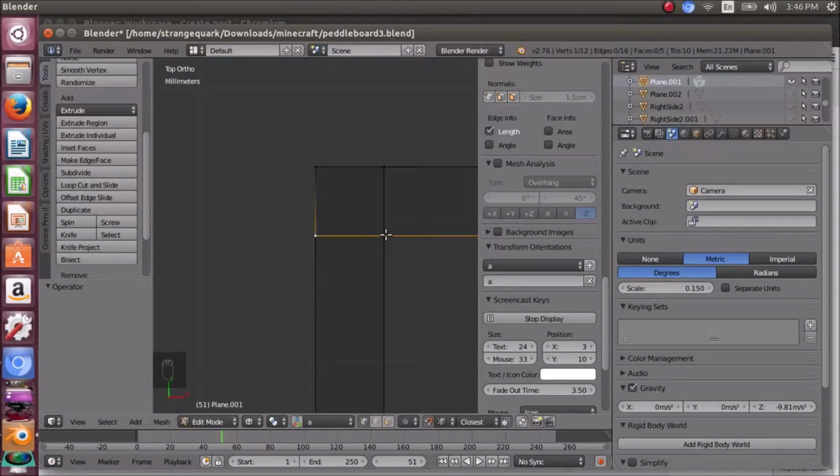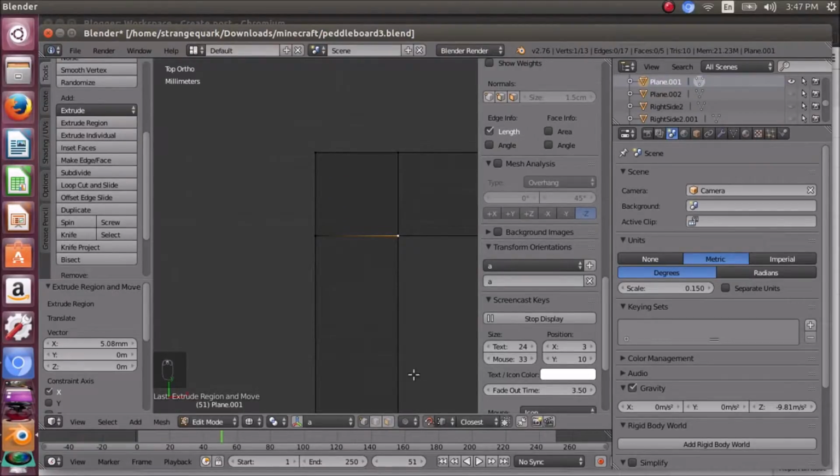So I'll go ahead and select this vertex here and we'll extrude it on the X-axis, and then I'll just run the mouse cursor up to the vertex, and lo and behold, it translates or extrudes on the X restricted axis to exactly that position. Snapping is an extremely handy tool because it'll save you a lot of numpad work once you get your vertices set up on your mesh, so you don't have to remember what you typed in for an actual extrusion